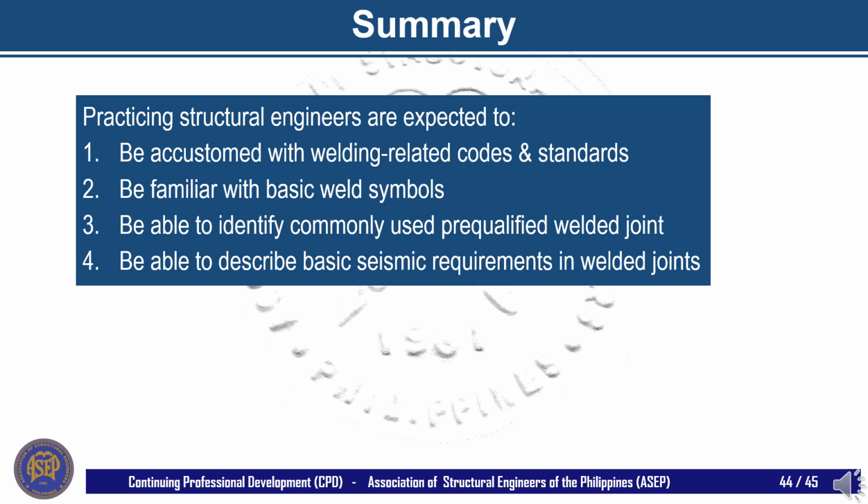In summary, practicing structural engineers are expected to be accustomed with the welding related codes and standards. Second, be familiar with the basic weld symbols. Third, be able to identify commonly used prequalified welded joints. And lastly, be able to describe basic seismic requirements in welded joints.